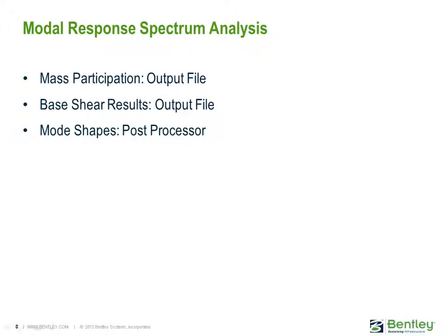After you create your dynamic masses and also your dynamic loads that you're going to be using in your modal response spectrum analysis, you are now ready to perform the analysis and review the results. Now typically in STAAD.Pro, the process for doing a modal response spectrum analysis may be an iterative or trial and error analysis, meaning that we will perform our first analysis and then we will check our results to see if they are in compliance with the ASCE 7 requirements.